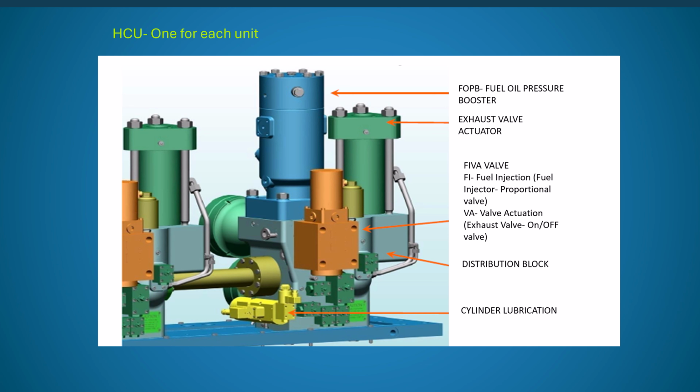And this is called cylinder lubrication. This is the alpha lubricator, but it is also hydraulically controlled. But it does not get hydraulic oil for operation from the fuel valve; it has a different system. It has basically a solenoid valve and allows the oil to enter. One SU to another SU is connected by a double wall pipe, hydraulic pipe,